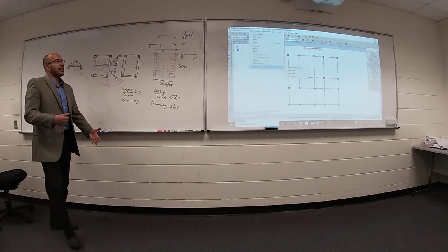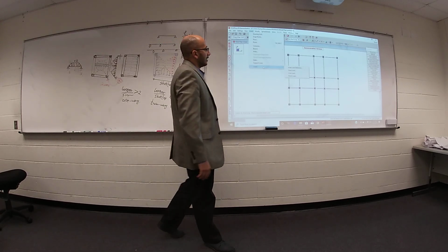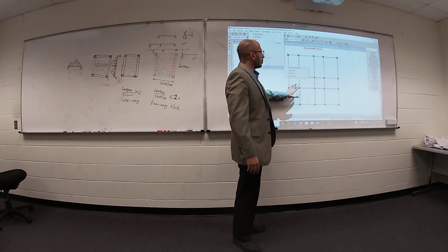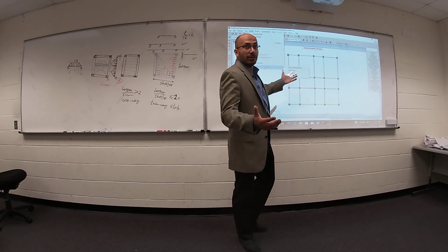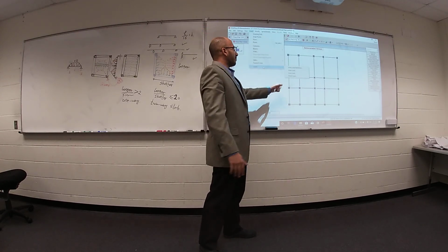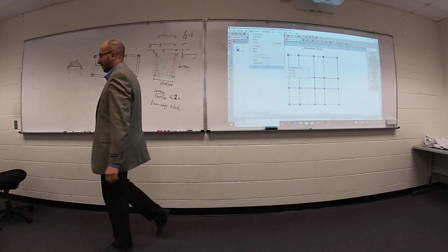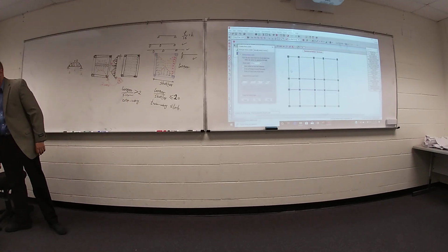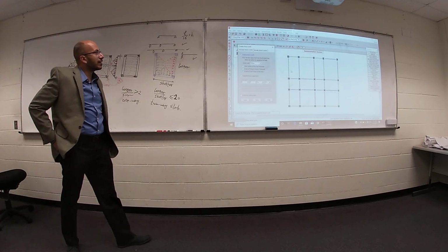I would like to define loads in which form: point load, just at point, line load, just on line, or area load. Area load. I need to define live load as an area load on your slab. So area load. How can I define my area load?